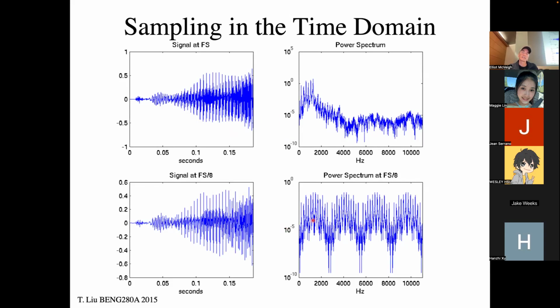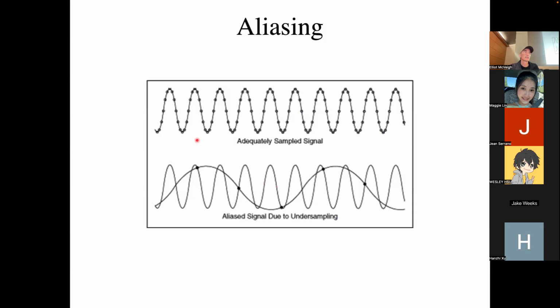No. So once this has happened, once you have undersampled here by this factor of 8 and you create this Fourier transform, this is really as much of the spectrum as you know right here, right? And then the rest is just replicants of that. And there's no way to magically recreate what's out here, because you haven't sampled it. So you just don't know what it is, right?